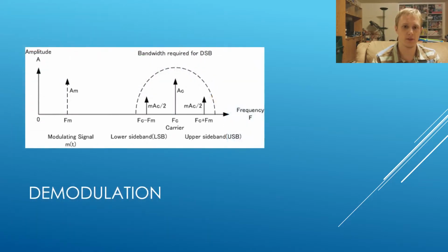Now let's look at the mixer from the perspective of 312. The signal undergoes a process called demodulation. The picture shows this process in the frequency domain. When the received signal is multiplied by the carrier frequency, the signal's frequencies are placed at a frequency the carrier frequency away. So if the carrier frequency is 20 MHz and the signal frequencies are around 20 MHz, the signal frequencies would be placed around 0 Hz, 40 MHz, 60 MHz, etc. The low-pass filter that comes after the mixer then removes the higher frequencies, leaving only the frequencies around 0 Hz.